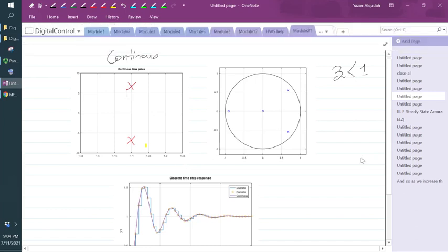We have two poles, one at negative 1.4 plus or minus, and the other root is around 7. So I have two roots in the left half plane that belong to an underdamped response. I know they're underdamped because these two roots have an imaginary part.